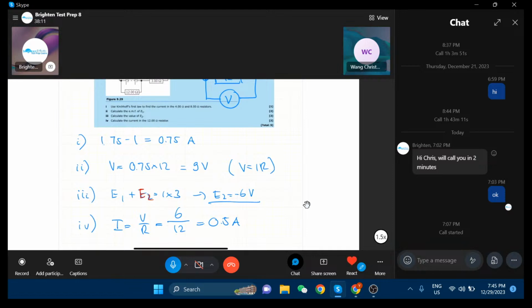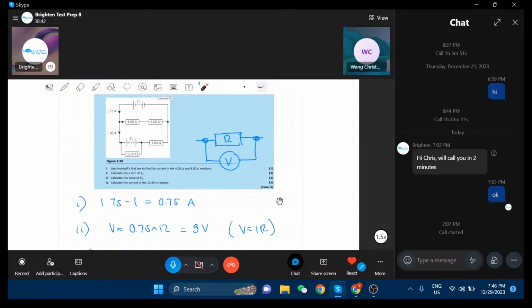And there must be, because we have another split here, that's another cross check, which we don't do, but we can say, well, this is another split because we have something here, and we have something here, right? So that must be coming together again, so to speak. So if we have 0.5 amps here, we should have 0.5 amps there as well. Because one in, one out. But we have a split.